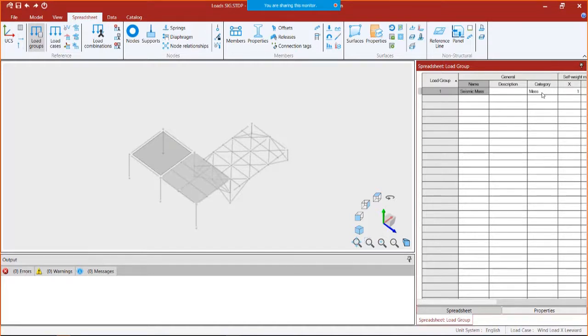Now the advantage about creating your mass on your structure, just as an aside, is that when you create the mass of your structure, that mass reference load case will be able to be used by multiple areas of the program, including considering your static self-weight for static seismic loads. It can also be used to consider your seismic mass. It can also be used to determine what the dynamic mass of the structure is for a dynamic seismic load. It can also be used to calculate the center of mass of any floor system if your model does contain a rigid